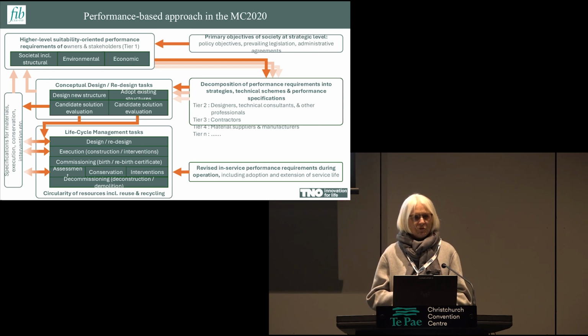In the model code, you will find provisions for assessment of structures that have corrosion, alkali silica damage, and freeze-thaw damage. And again, this is very relevant because the structures have these issues, and we must know how that sometimes material-related degradation, sometimes other aspects of degradation do affect actual capacity and safety.